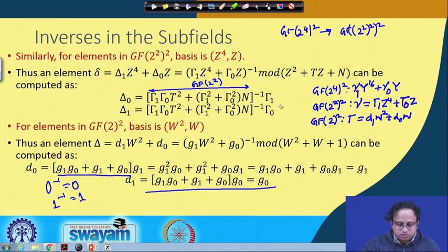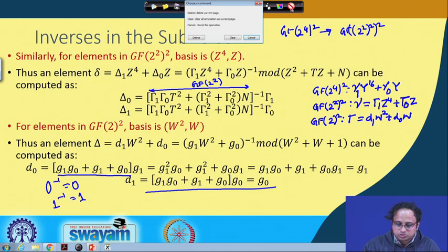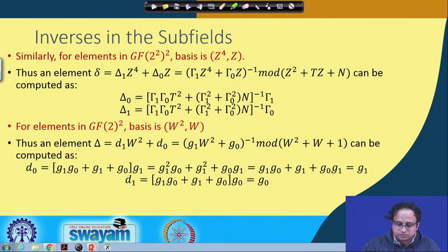And you can also observe that this means the squaring in this field will also be equally easy. So the squaring and the inversion, both in the normal basis in the lowest field, are actually free, unlike your polynomial basis where you probably need some XOR gates. So that is an incentive for going into the normal basis.